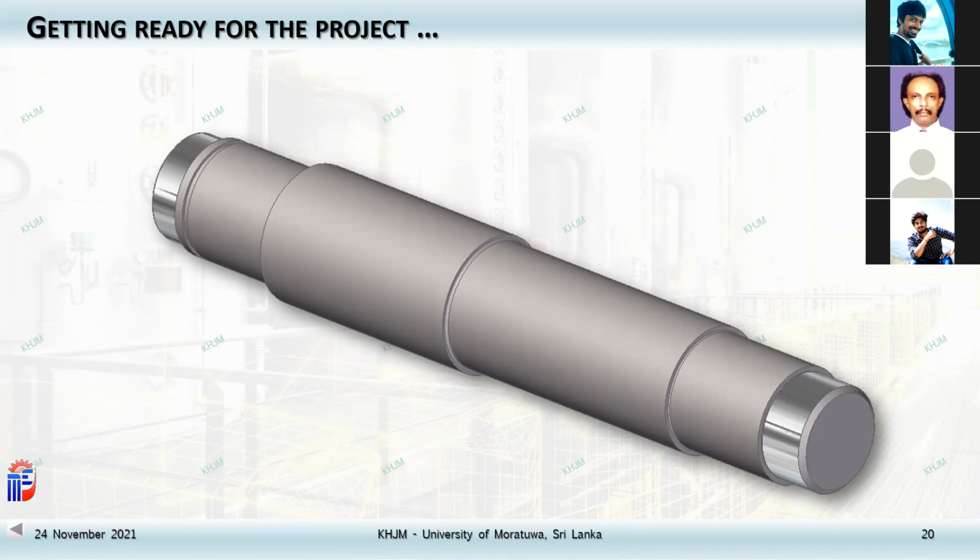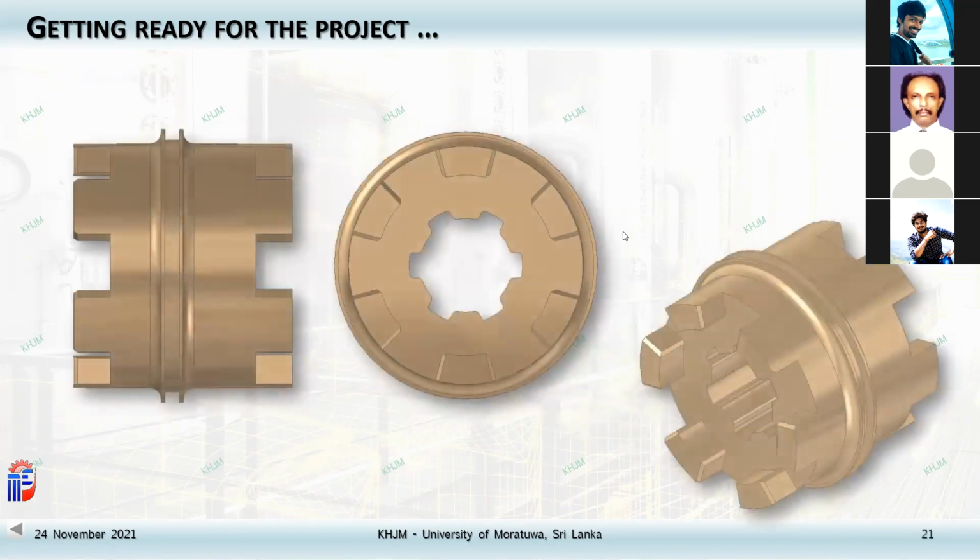Remember, inside the gearbox, I need to locate them exactly. How do I do that? I can't just take a scale, measure the distance, and fix the gear wheel. Once this gearbox started, it will move here and there. It will move here and there, right? You see, this is what you call the dog clutch. It depends on what sort of a mechanism that you use to shift gears. Right? All these things need to match.